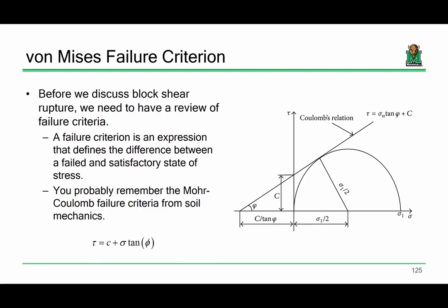For instance, if you have a stress element and you're looking at a foundation, or at stress in a soil, when does it fail? Well, it's not as simple as the stress hitting some value, because you've got normal stresses and shear stresses going on at the same time. If it's a clay, it has a cohesion value, angles of internal friction, all this stuff. There are a lot of different parameters. So how do you determine whether that element experiences failure? Well, it depends on what we call a failure criterion. I promise you have seen at some point a failure criterion related to soils.